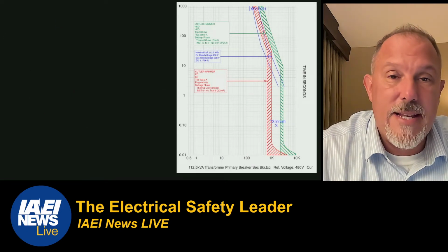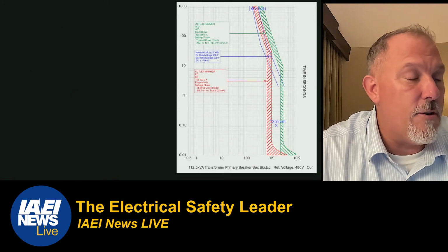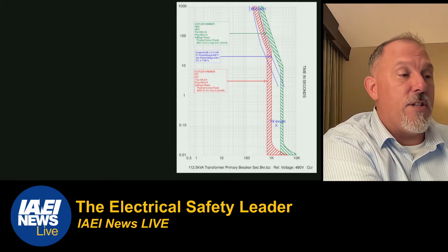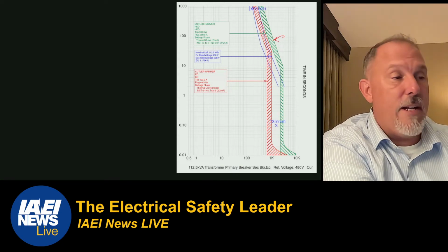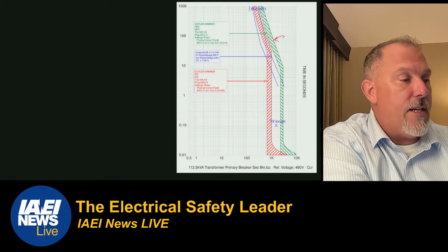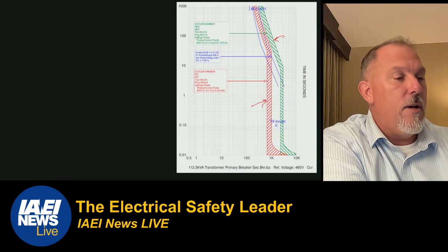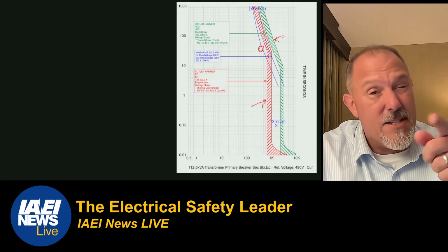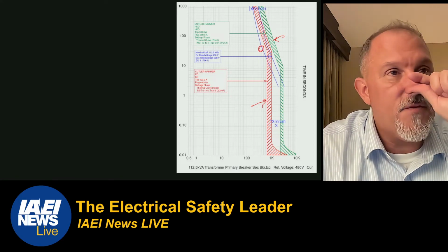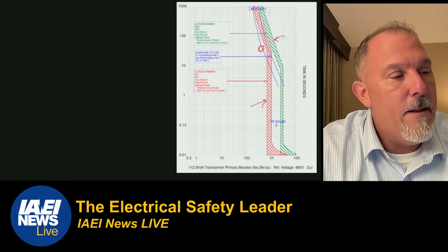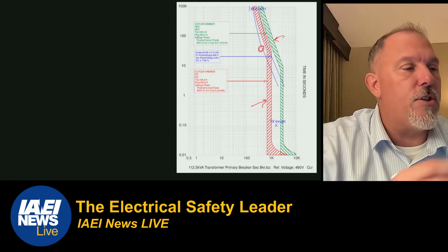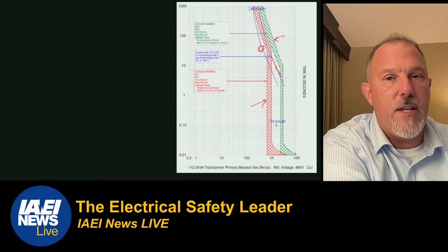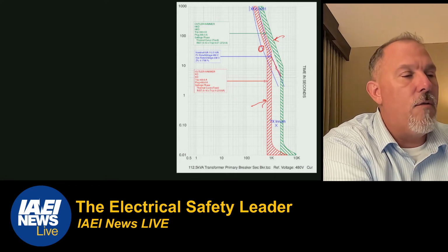Now, this is my secondary overcurrent protective device, if I do a circuit breaker, this is my maximum, my 250%. Remember, 250% is well to the right of the damage curve, and this is a 400 amp circuit breaker. But you might say that now this second damage curve, I talked about this a little bit. The second damage curve is for unbalanced faults. What we would typically do with these transformers is only plot the one. So I am sort of confusing things a little bit, but I get good overload, in my opinion.